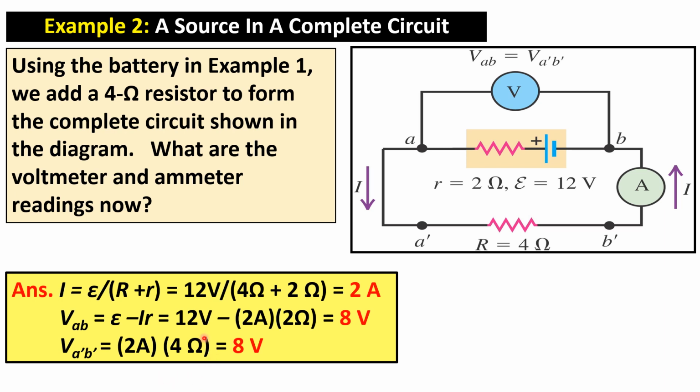Again, using this formula for determining the current in this part of the circuit. For example, what is the current from point A around this, passing through the big R, passing through the ammeter, and then directly going into the negative terminal of the battery, as indicated by this arrow that symbolizes the flow of positive charge, which incidentally is what we call conventional flow of current.